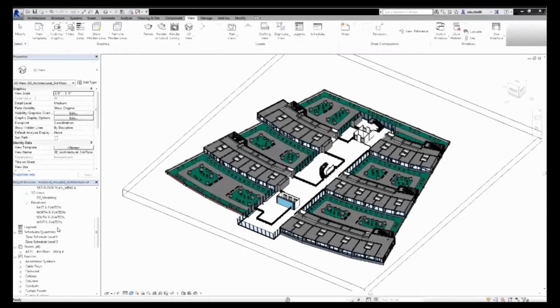And in addition, in Navisworks 2021, you can now switch back to your model from Revit, meaning when you select an item in Navisworks, you can right-click that object and choose switch back. After clicking switch back, it will bring you to a switchback view directly in the same model that you have imported.